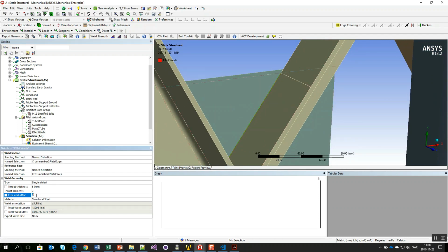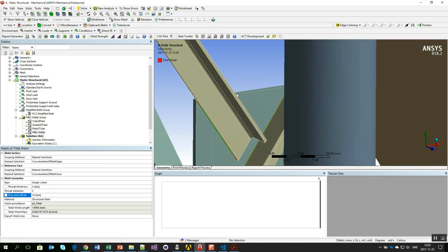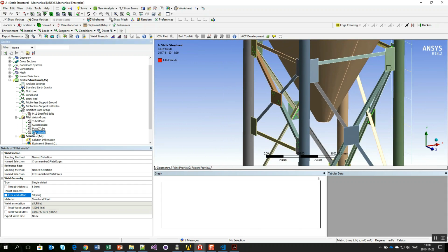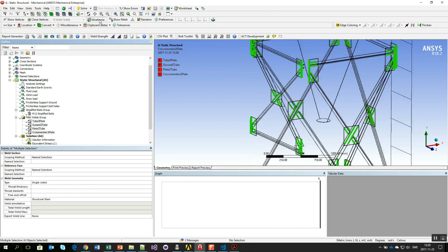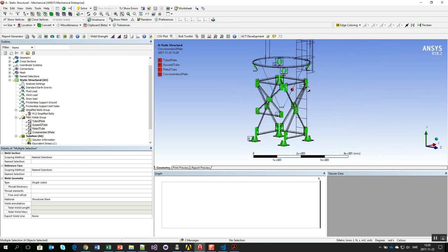So if I specify this free end offset, the weld is indented and not hanging out in the air in these places. So these are now all the welds needed for this frame.